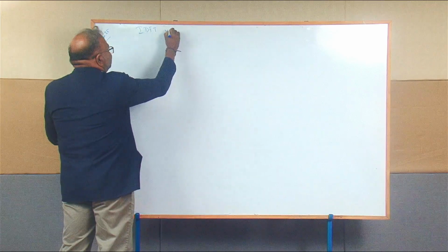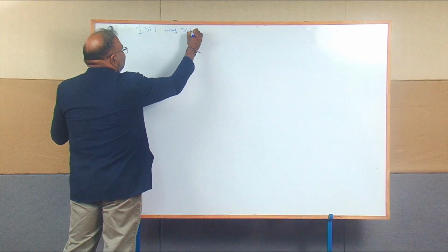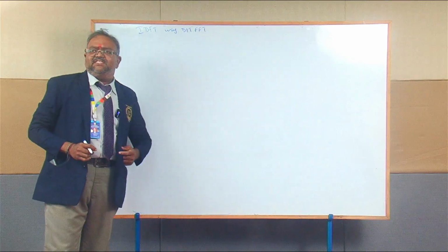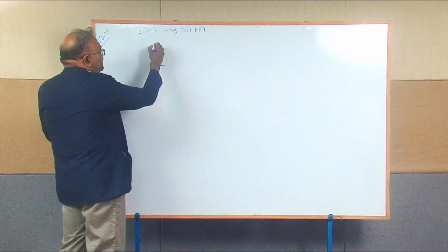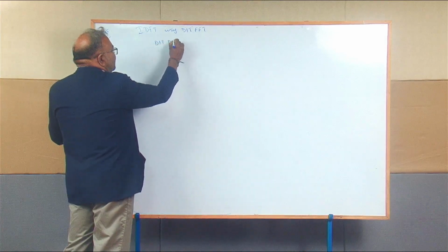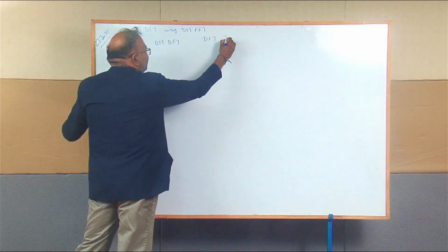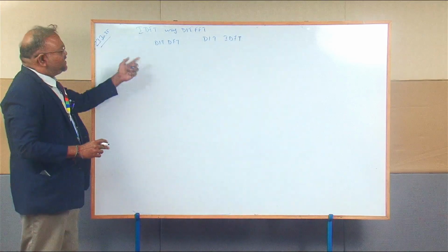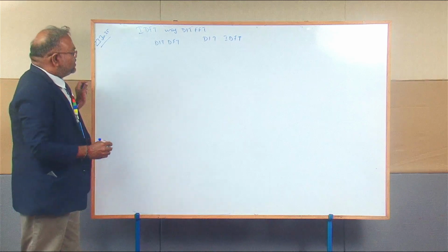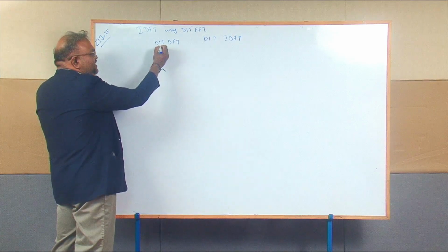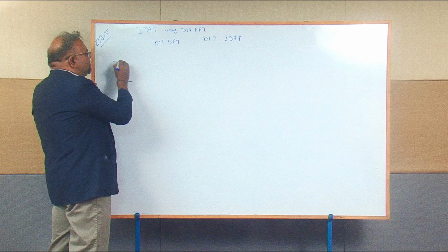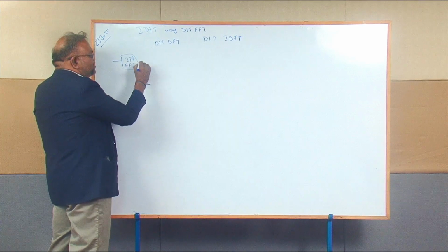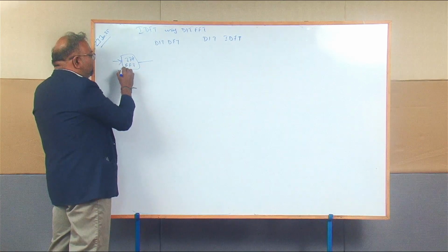IDFT using DIT FFT. So, first in butterfly diagram, what is the difference between DIT DFT and DIT IDFT? In our previous video we have seen the DIT DFT using butterfly diagram. DIT is decimation in time. First stage we will have a 2-point FFT. This is stage 1. Before that the twiddle factor will be multiplied.